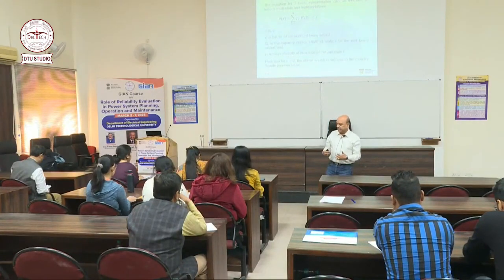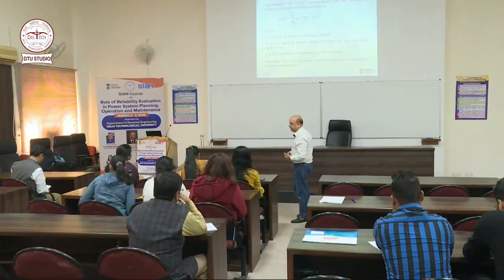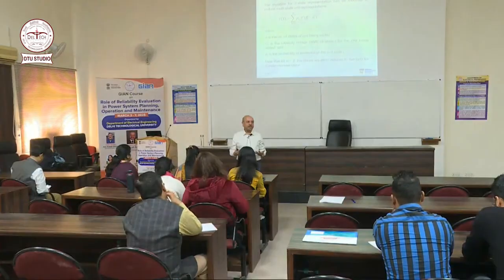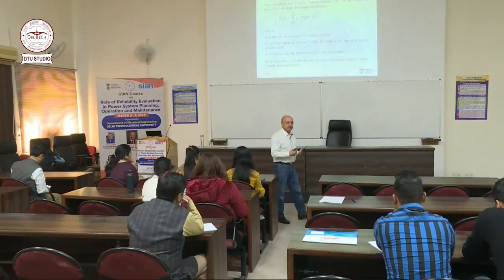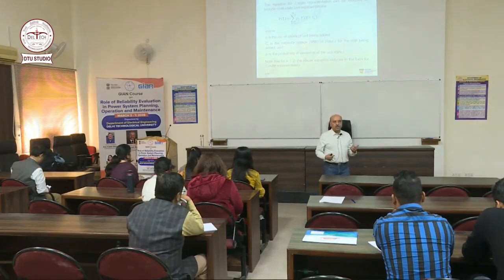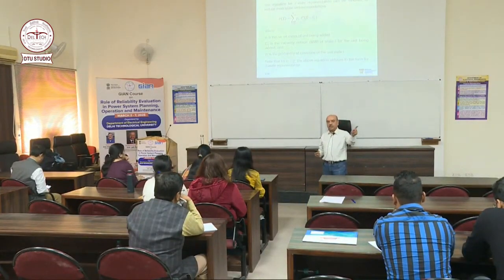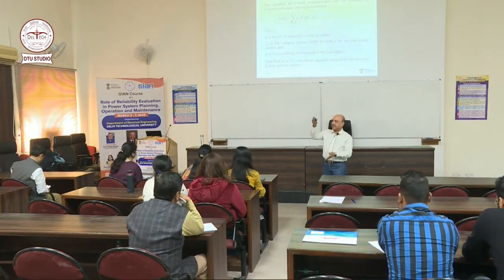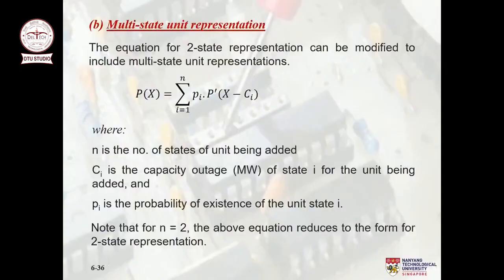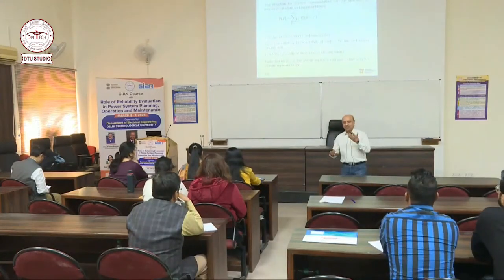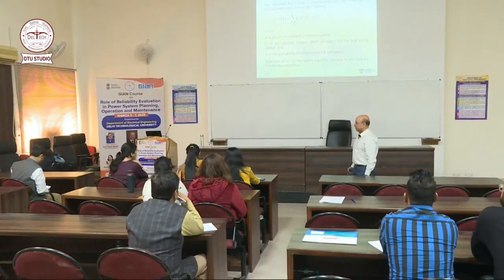We also said that instead of using state probabilities, we can use cumulative probabilities, and that is sometimes advantageous because we can directly find the cumulative probability of X or more megawatt out of service by just looking at one value rather than adding up a few values. So we spoke about that. We looked at a few examples, and there were some exercises for your doing pleasure. And hopefully you are up to speed with respect to what we have done.